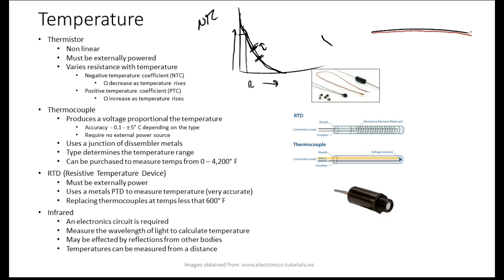Yeah, they're going to expand differently, which is going to cause it to do what? It's going to cause it to bend. Thank goodness. This is one of the primary ways circuit breakers work. We run the current through a bimetallic strip that's got a little bit of resistance. As current goes up, it heats up. When it gets to a certain temperature, it trips your breaker, right? You understand that? A lot of your old thermometers, thermostats, use bimetallics.